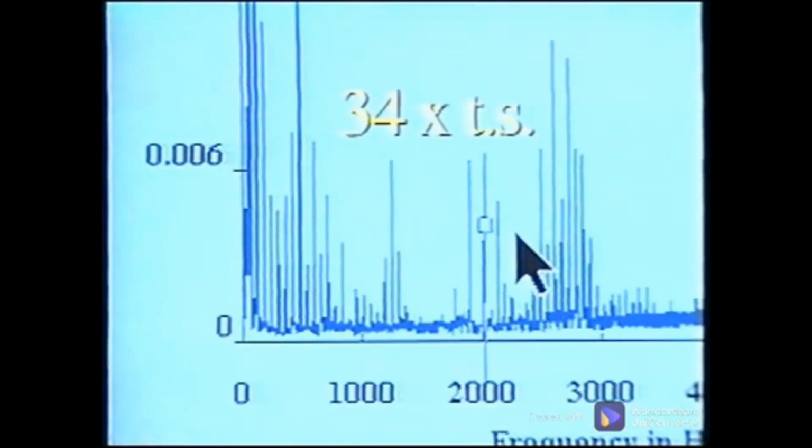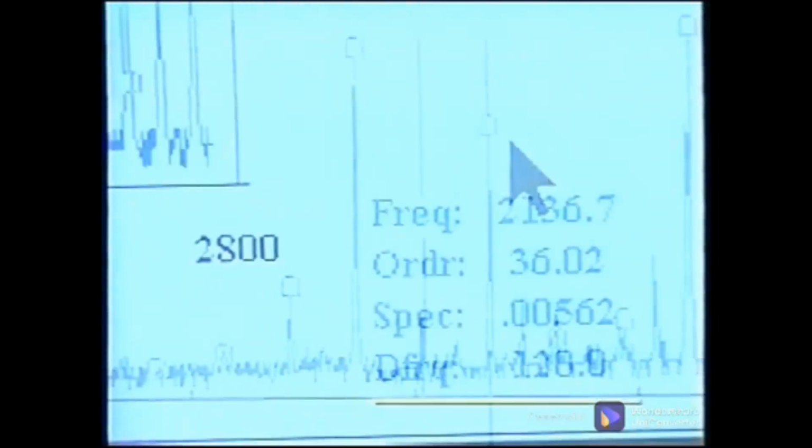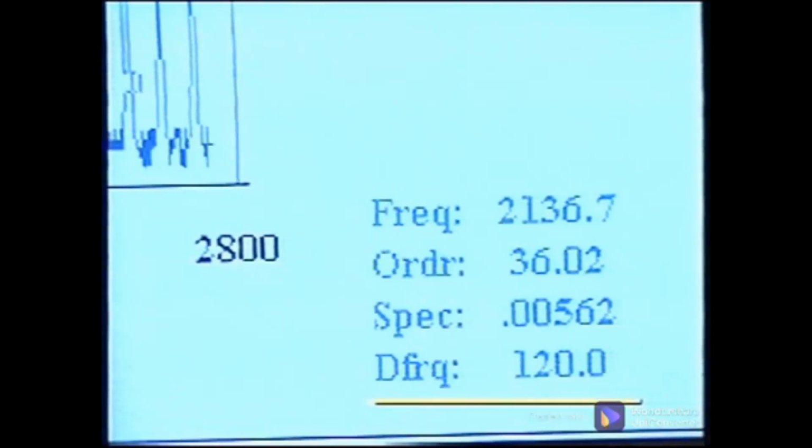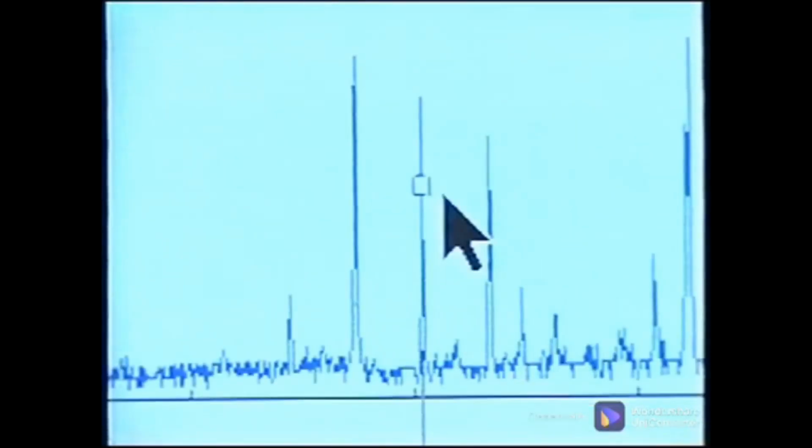The motor has 34 rotor bars, so high-resolution data was collected around rotor bar pass frequency. There are several peaks around 34 orders that are spaced 120 Hertz apart. These are sidebands spaced at 2 times line frequency. A rotor bar problem was suspected.